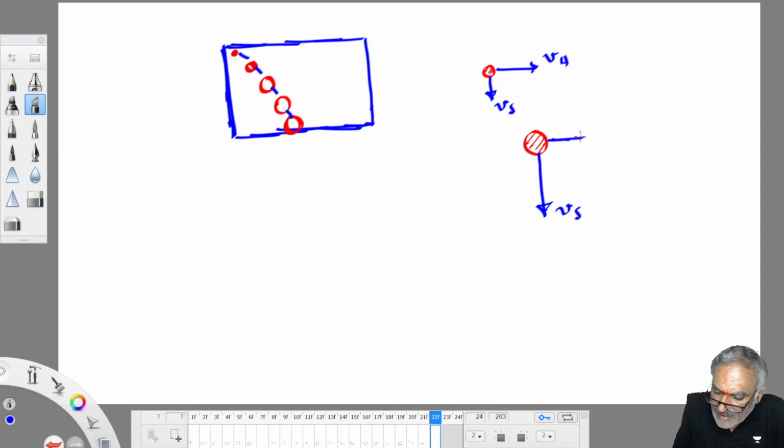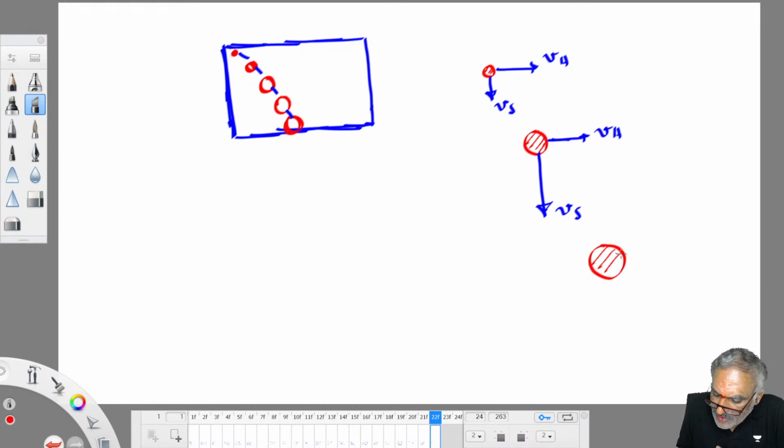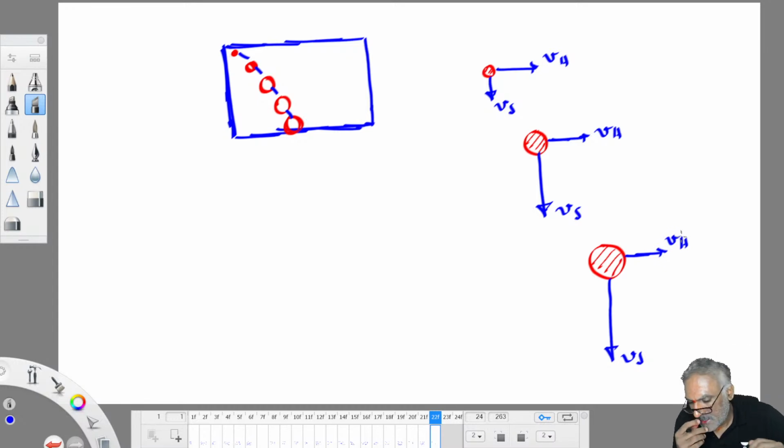Suspended particles are discrete particles. No change in settling velocity. Then as some more distance it travels, it grows into some more size. So settling velocity keeps on changing, but flow velocity would remain same. It is a rectangular tank.